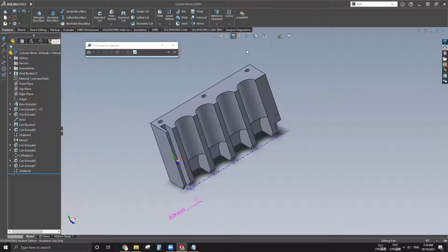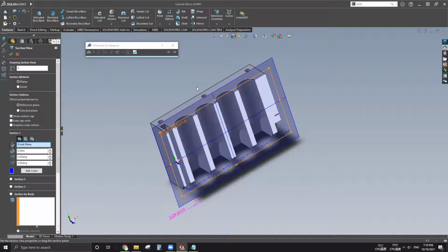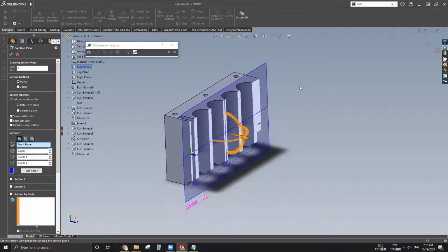And what did you click again to be able to get that point of view? Cross section. And how do we make it for that specific section? Once you have the component ready, just click that, and then it will tell you which plane you're selecting as a reference plane to cut it through, and you can set up whatever you want.